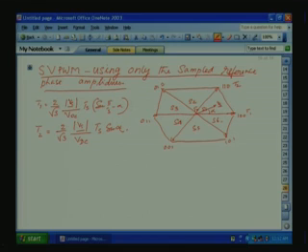See this one, we also know the equation V alpha is equal to 3 by 2 Va and V beta is equal to, from the alpha beta transformation, root 3 by 2 times Vb minus Vc. This also we have derived. Now, how can we get this T1, T2 in terms of Va, Vb and Vc?